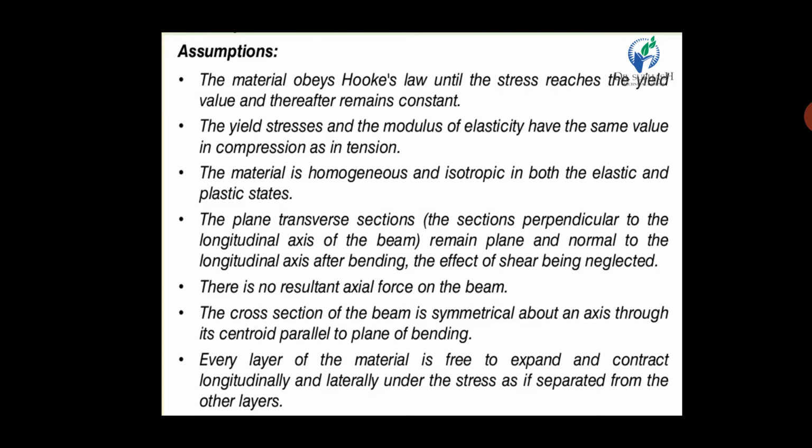Fourth, plane transverse sections remain plane even after bending, and the effect of shear is negligible. Fifth, the cross section of the beam is symmetric about an axis through its centroid parallel to the plane of bending. The influence of normal and shear force on the plastic moment is not considered. There is no resultant axial force on the beam. The material is assumed to be sufficiently ductile to permit large rotation of the section. And last, no instability occurs in any member of the structure up to collapse.